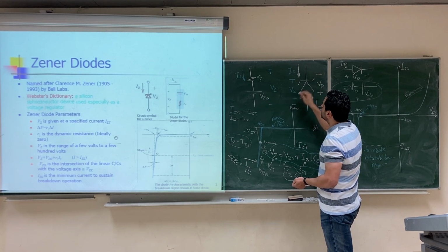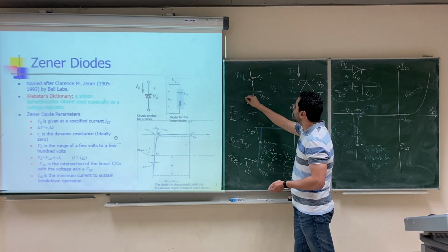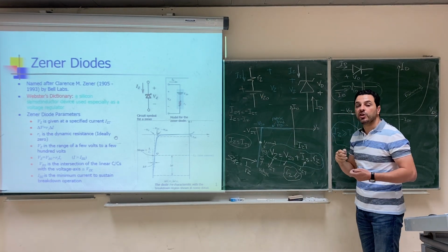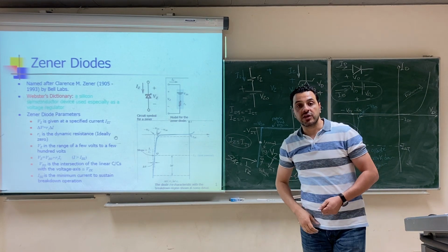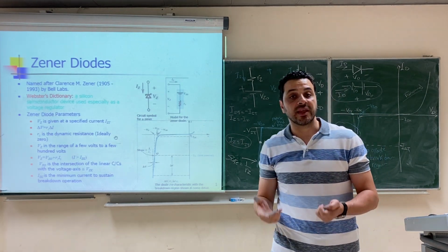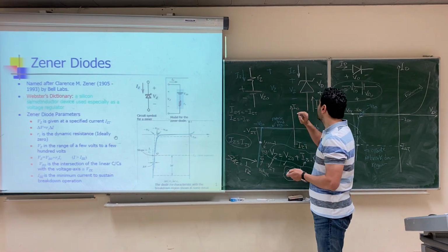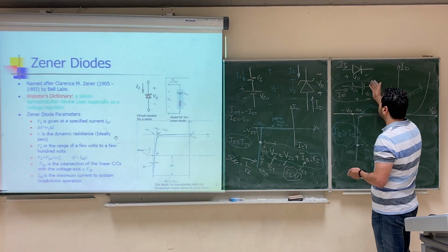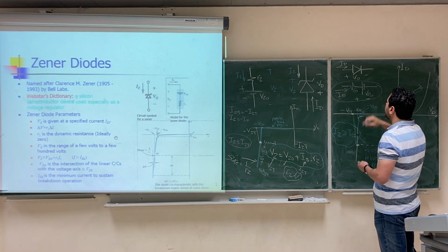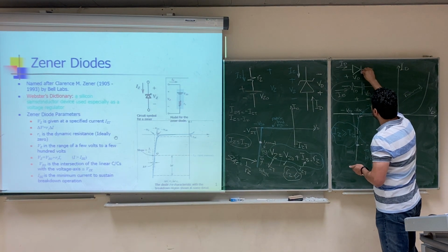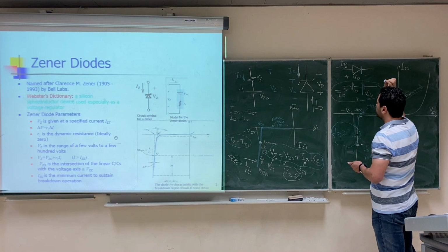Okay? Down. So the direction of the battery will be up. Okay, Shabab? So you have to be careful when you model the diode in the forward region, the direction of the battery will be different from the direction of the battery in the breakdown region. In the forward region, I'll repeat it again, the direction of the battery will be negative towards the negative, positive towards the positive.